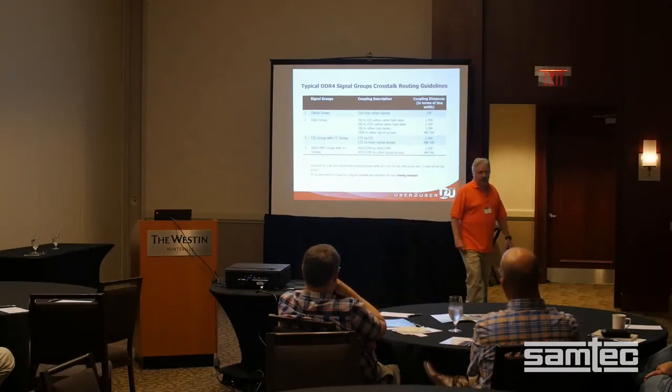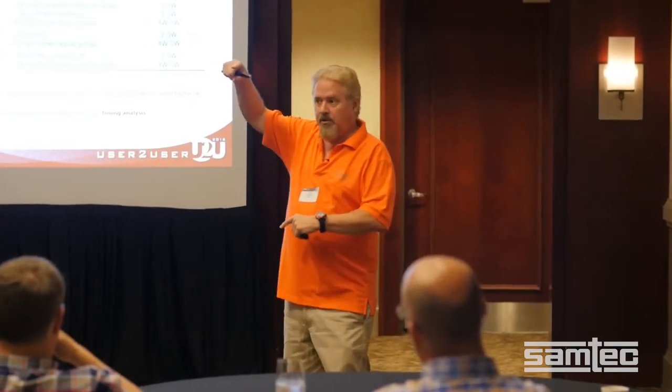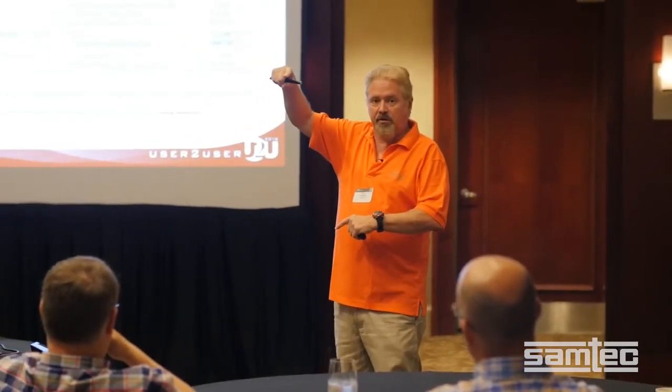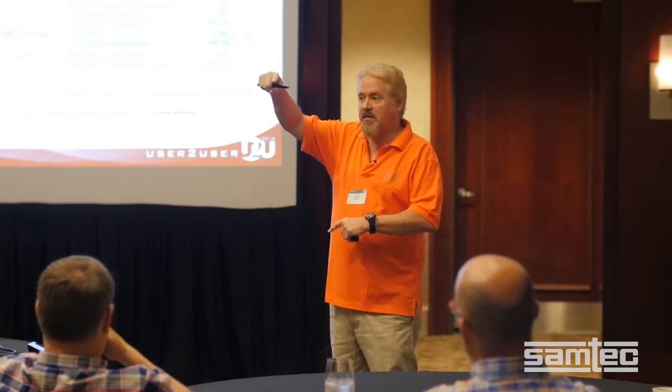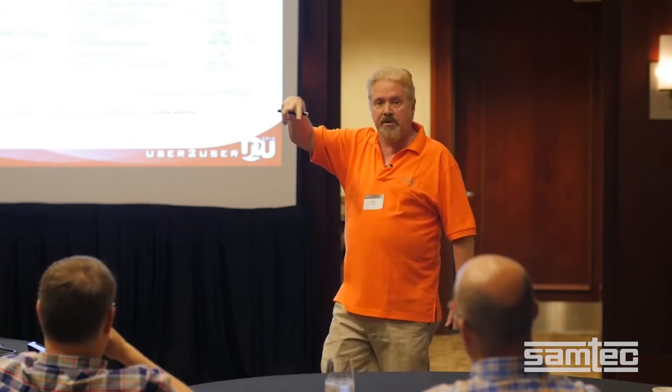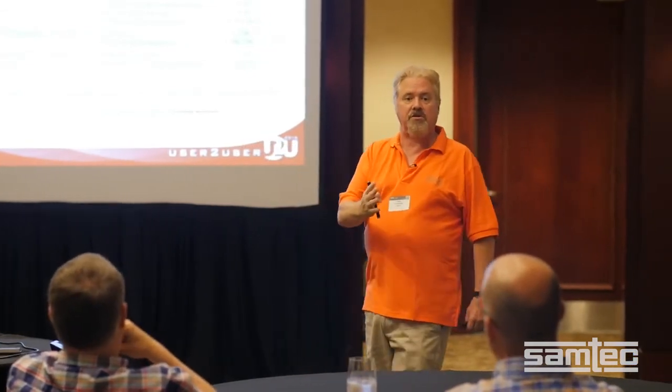They're not minimum. Why can't we make them minimum? Crosstalk just goes up. Especially, remember, on your outside layers, remember those are microstrip, the crosstalk has what? Forward crosstalk, which grows with length, linear length. You double the length, you double the crosstalk. On the inside layers, there's no forward crosstalk. It's only reverse crosstalk, and once the crosstalk goes up to what we call the critical or saturated value, it never gets any larger, which is nice. You make it this long, you make it this long, they have the same crosstalk.